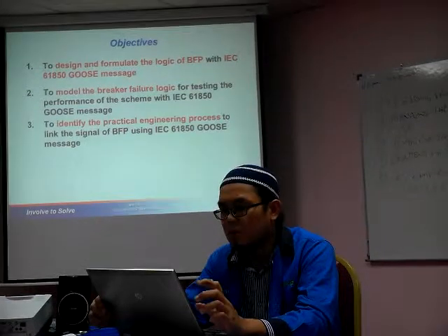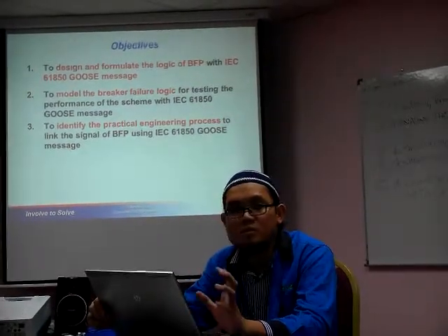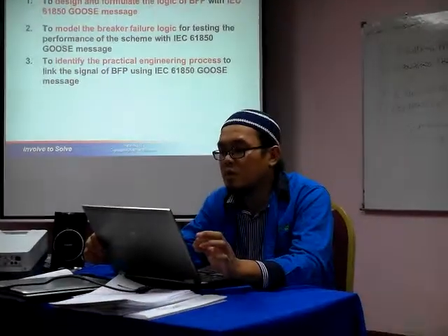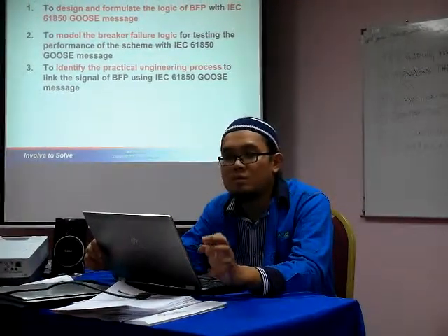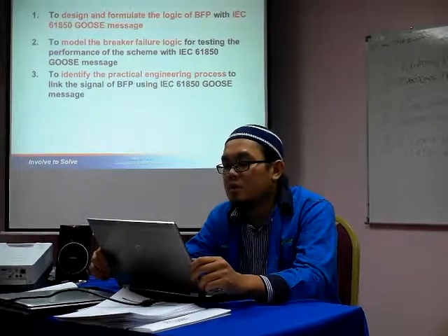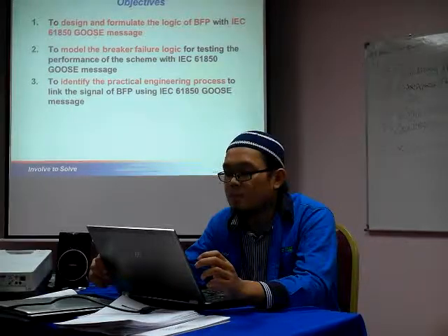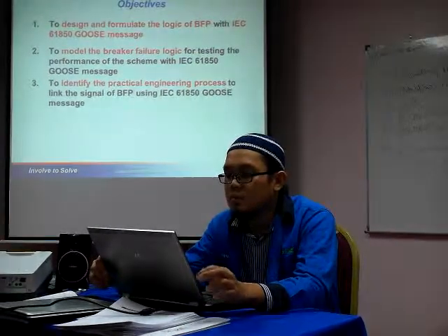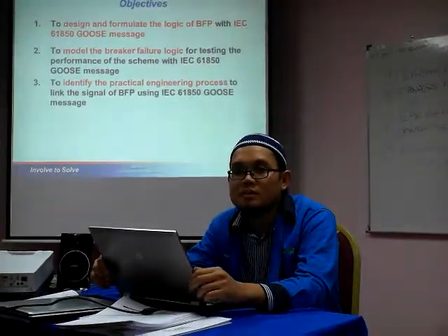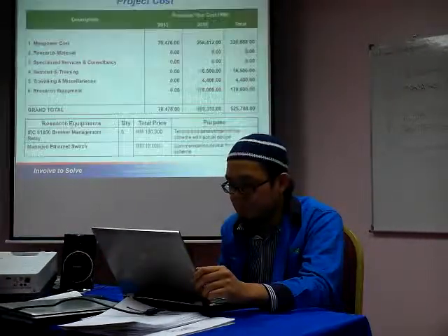Number 2, to model the breaker failure logic inside some power system software, for testing the performance of the scheme with IEC 61850 GOOSE message. And third, to identify the practical engineering process to link the signal of the breaker failure protection using IEC 61850 GOOSE message.